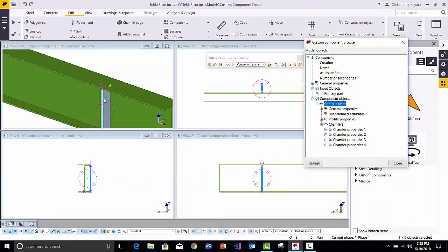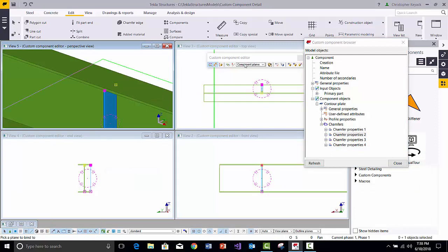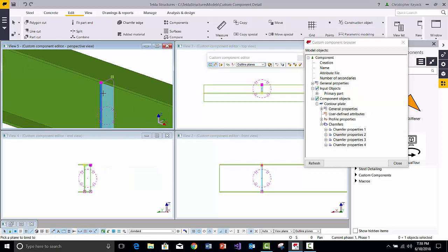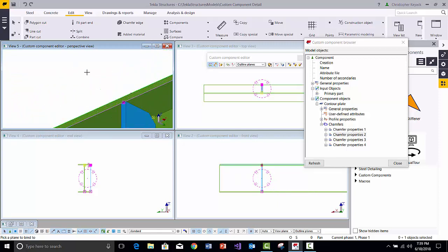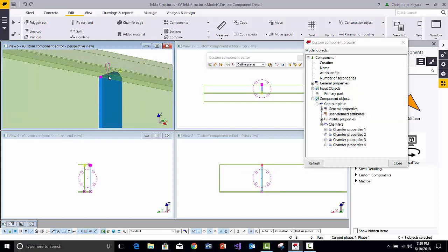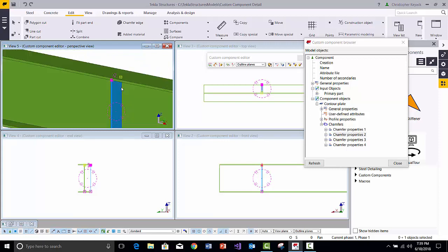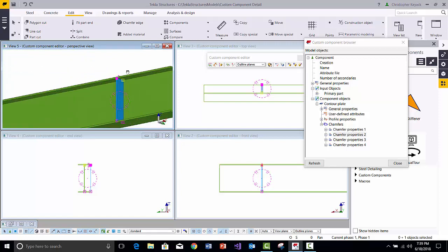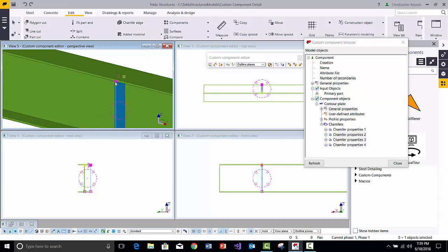All right, let's go ahead and select on this point again. We'll right click and say bind to plane, and this time we're going to bind to the outline planes. So the outline plane that we want to get to is the bottom flange, or sorry, the bottom of the top flange. So we'll pick that, and now we have another binding in here. Now, one thing that's important about doing bindings is that for you to select the surface to do the binding, you actually have to be in rendered mode. If you're in wireframe or if you're in even translucent, it won't necessarily allow you to do the bindings. So whenever you do a binding here in the model, you want to be in solid.